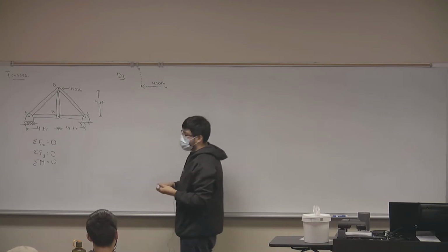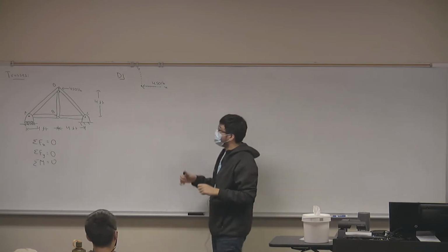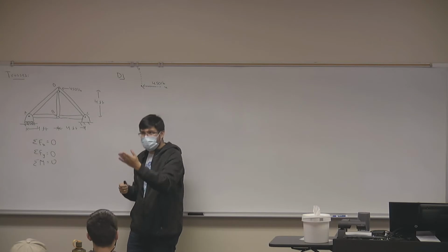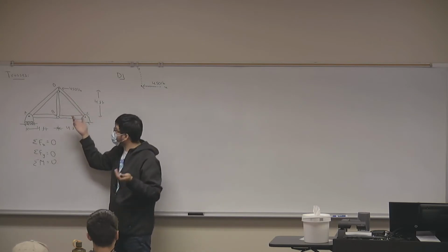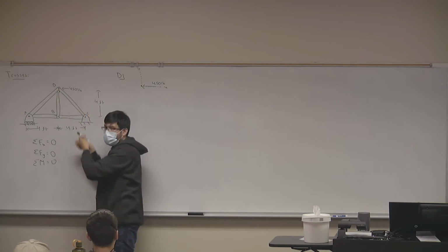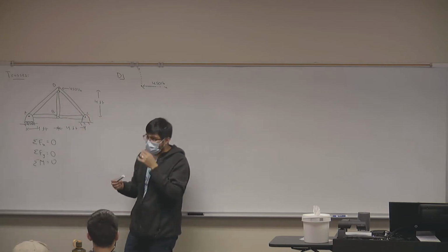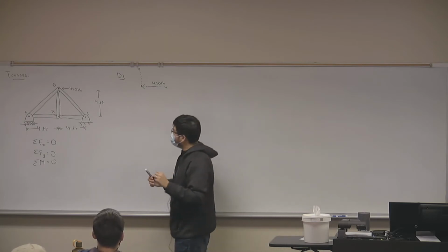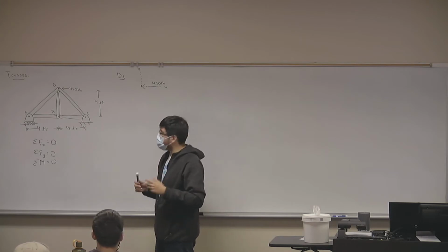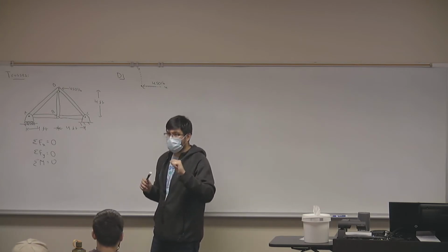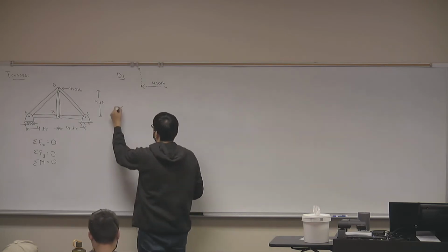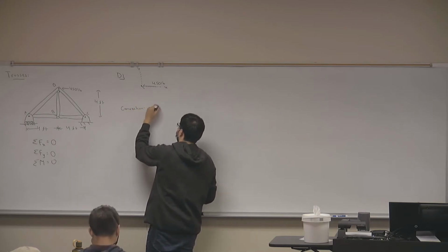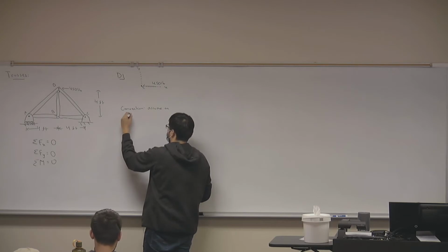Now, there are different conventions on how to draw these initial forces. Of course, you can find out these forces conceptually just looking at it. I mean, you just said, this force will be a tension force. It makes sense, right? You're pushing this joint away from it, it'll be tension. But let's say that it's not that intuitive, right? Let's just say for our purpose that it's not intuitive. The convention that we'll use here is the convention that most textbooks use, is to always assume an outwards or a tensile force, okay? So convention is to always assume an outward or tensile force.